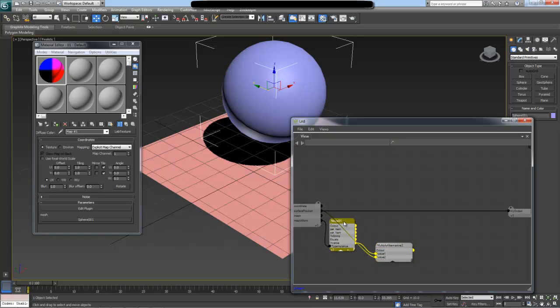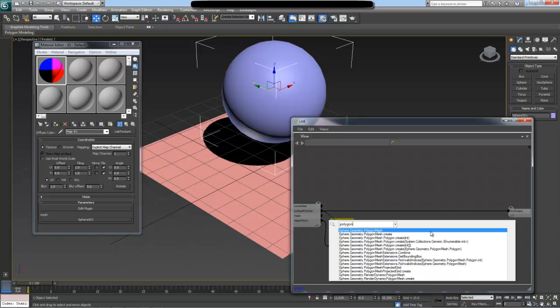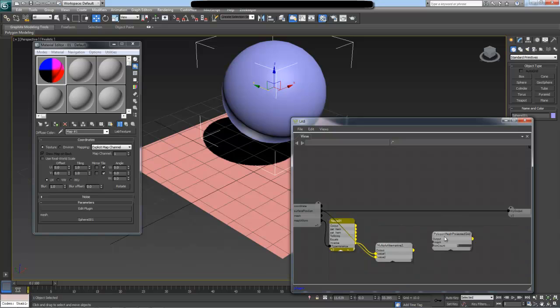So now we also will create an object called polygon mesh projected grid. And from a previous tutorial, you can remember that this is basically a utility class which allows you to take a mesh and do operations like determining whether a point is inside of it or measuring a distance to a mesh. As the mesh, I'm going to provide my input.